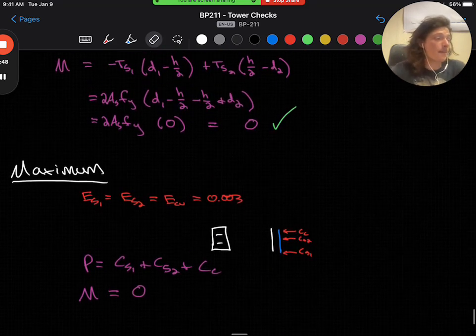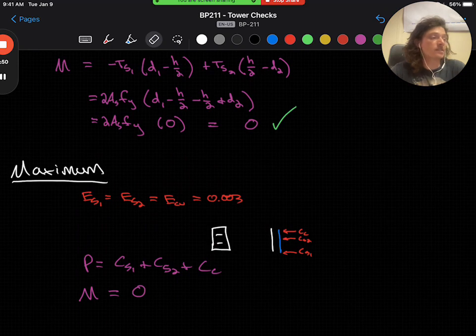We can find maximum by setting both steel strains to the concrete compressive limit of 0.003. Essentially, the member is in complete compression before yielding. We then use these numbers to calculate the rest of the terms to arrive at what our axial load would be. And the rest of the plot is then filled in with the values calculated before.